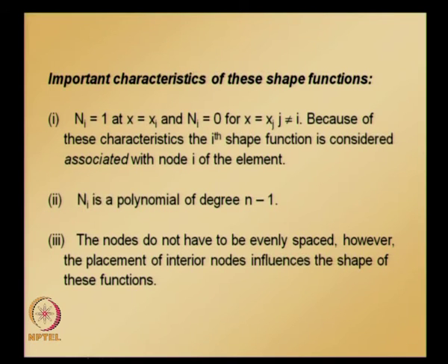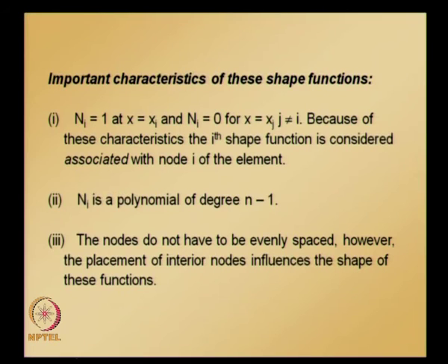So, here we have seen two ways of deriving shape functions. One is starting with a suitable polynomial, or you can use the Lagrange interpolation formula, but using the Lagrange interpolation formula, writing shape function expressions for any order element is much easier. So, now let us take some examples and apply this Lagrange interpolation formula.